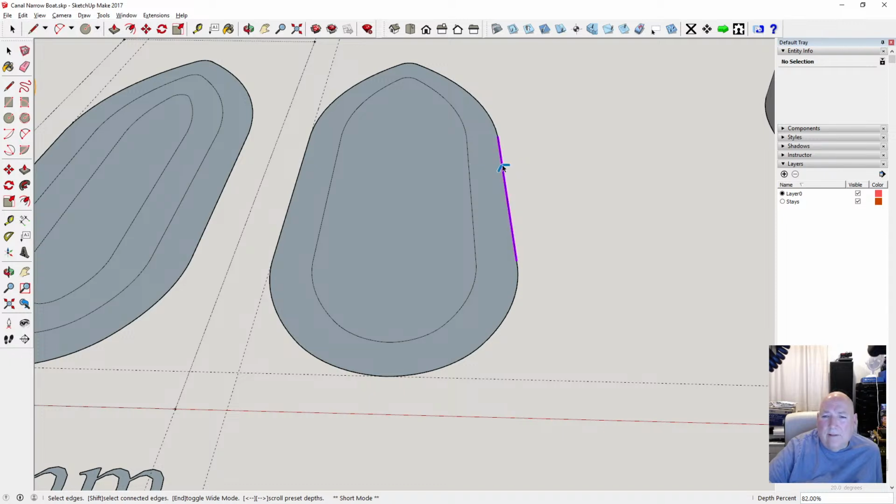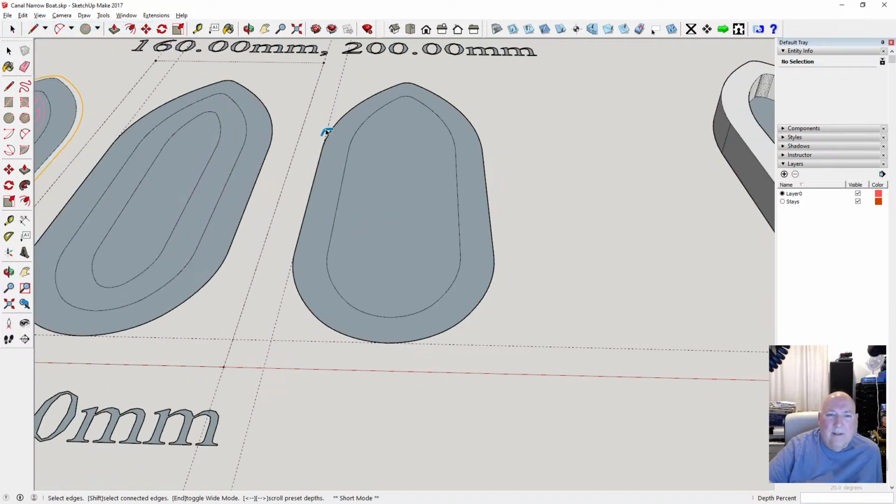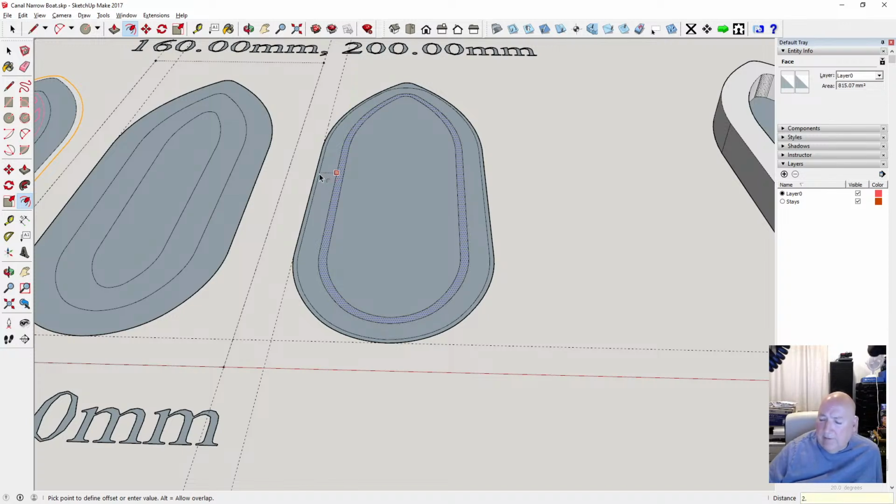You can go, it'll mill down the center. I think I had to do this before. Yeah, I think what I have to do, right, this is how I do it. What I do is I come out here and I go out to the center of the mill bit. Okay, which is a 5mm mill bit. So I go 2.5 and I go 2.5 and keep going.